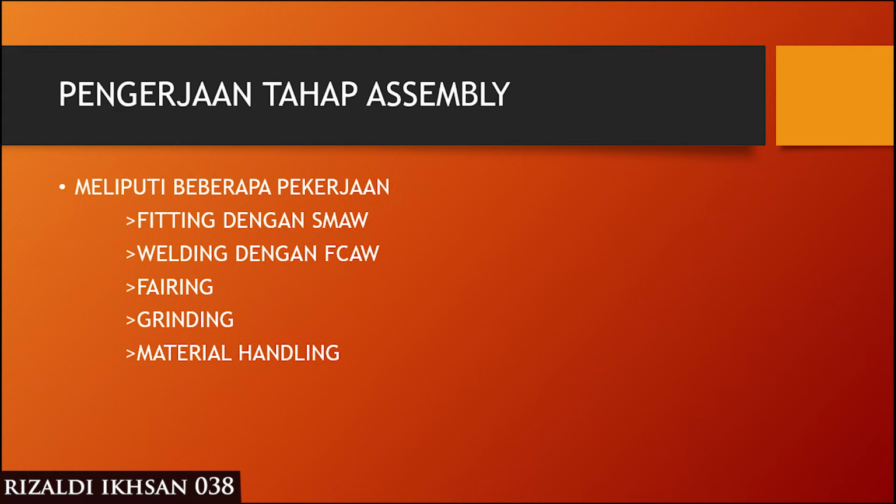The erection stage includes some work that can be said to be similar to the assembly stage. They are fitting with SMAW, welding with FCAW, fairing, grinding, and the last is material handling.